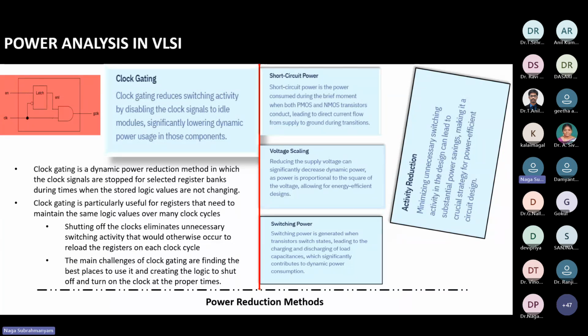See, we need to understand there are various power domains, right? Various voltage domains also, and various threshold voltages, multi VTH, multi VDDs. We try to reduce those. We need to have a very small number of VDDs, multiple voltage domains or multiple voltage thresholds.